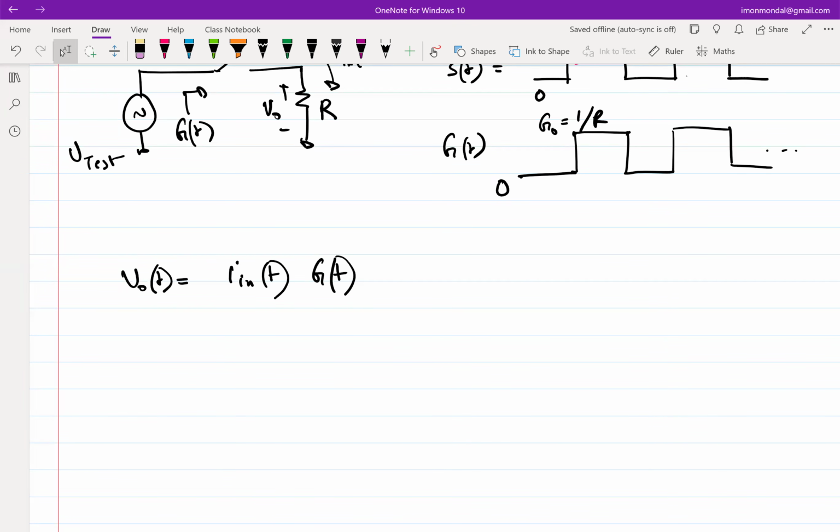So the next thing, since we know that a periodic signal, not an aperiodic signal, a periodic signal has multiple discrete frequency components, not spread across all frequencies, but tones, which essentially means I can break G of t into multiple tones, basically a Fourier series.